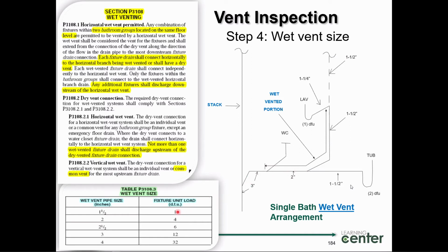Go to the table. 1 is no good. I could move up to 4 and size that pipe at 2 inches. 2-inch diameter is the pipe size here. And then, as you would expect, a water closet is a 3-inch connection. It has a 3-inch connection on it, and of course, it ties in accordingly at 3 inches at this point. And this is the end of the wet vent system. So this is all 3-inch going down.